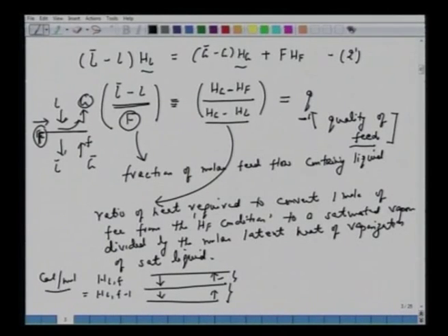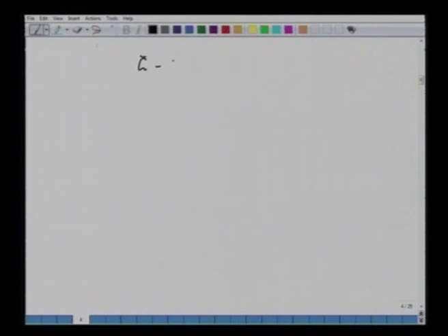Now the total calories, because molar flow rates are different here as the feed is introduced. Okay. So this is a definition for G. As a consequence, now that definitions, you can write G bar minus G as F(Q minus 1). You can also write L bar minus L as Q into F. All right.